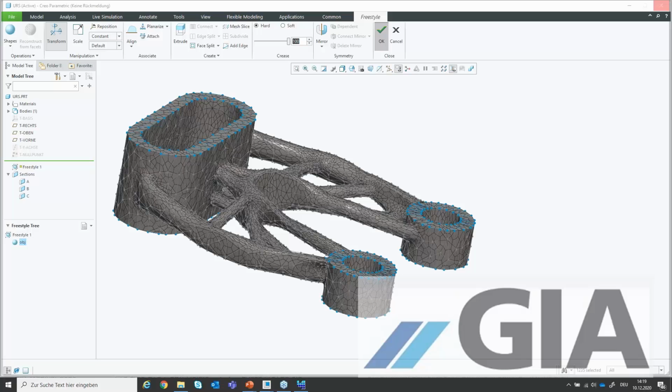Somebody asks: I have faced failure in export. Any tips to make it better? I would say the tip to make it better, I think this is GTO, you must use 7.0.20 when exporting these surfaces. This is really a nightmare, but quality improved in 7.0.20.